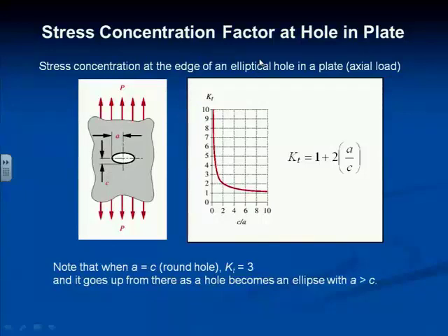So what's it going to do? It's going to yield. If it can yield, it'll yield. And it'll yield if it's ductile. If it's brittle, it's all over, it breaks. But if it can yield, what it'll do is yield and open the crack up and make the radius something other than 0 until it reaches equilibrium. And if in the process of doing that, it doesn't crack all the way across, it still holds together. And it reduces the concentration by changing its geometry by yielding.